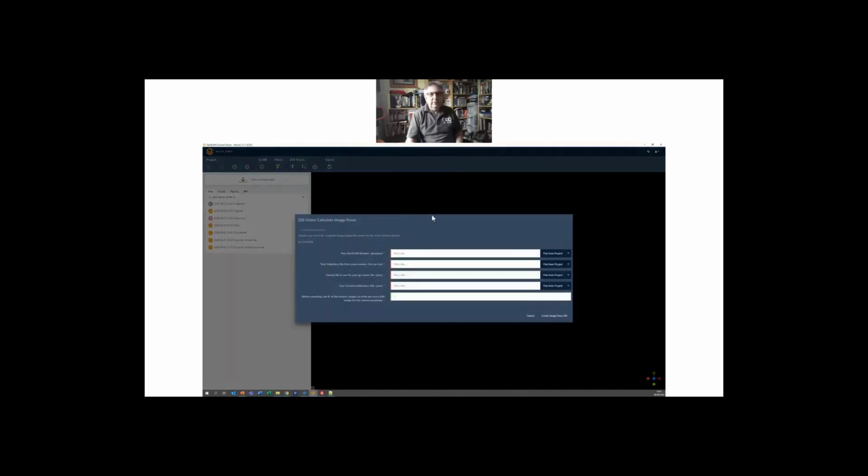So once the stitching is completed, then we can calculate the camera trajectory or the camera pose for each image. Again, within this workflow, we ask to pick the .GeoSLAM file. Again, that's really just to confirm that we have the right data set that we're looking in. So I can choose that one.